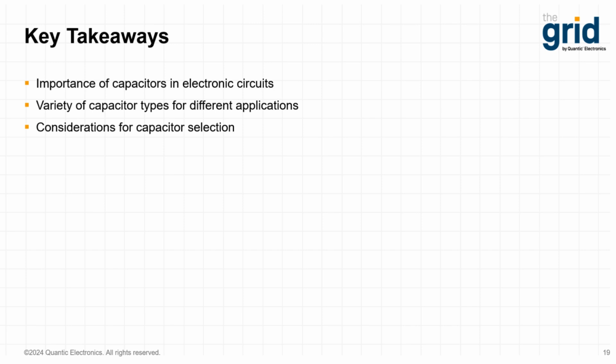Aside from the hard set rules of electrolytics being DC only capacitors and the frequency limitations of capacitor types, nearly every consideration of capacitor selection can be looked at as a trade-off between reliability, size, cost, stability, longevity, and overall performance. Each parameter must be carefully evaluated and weighted by the designer or engineer to determine the most effective solution for their given application. So capacitors are all around us. And as you can tell by today's presentation, they have a significant impact on many of the electronics that we use and rely on today.